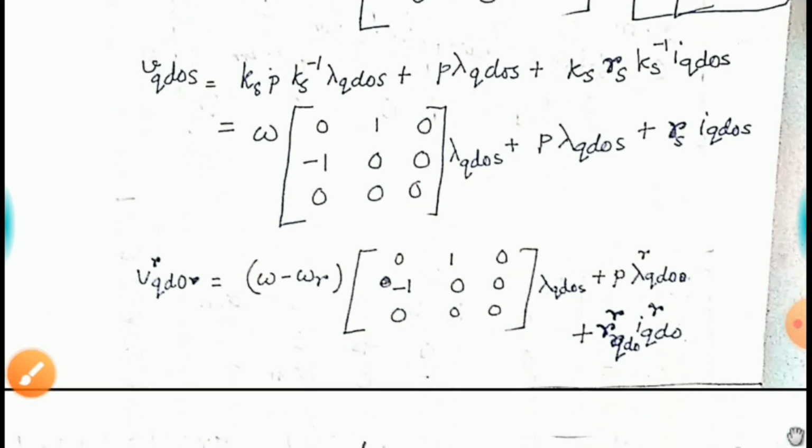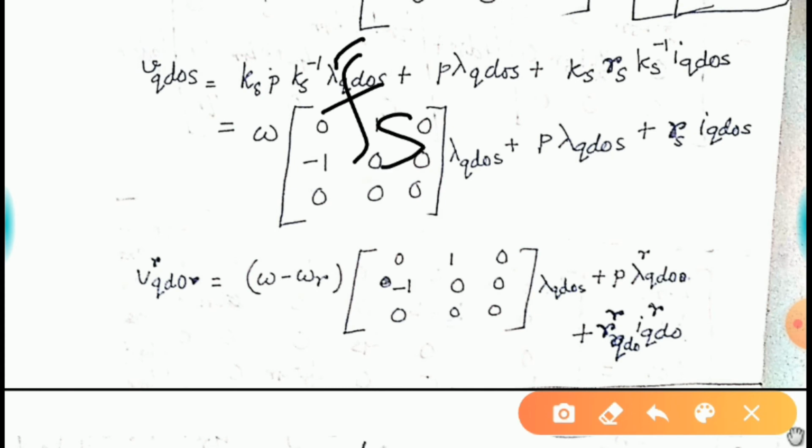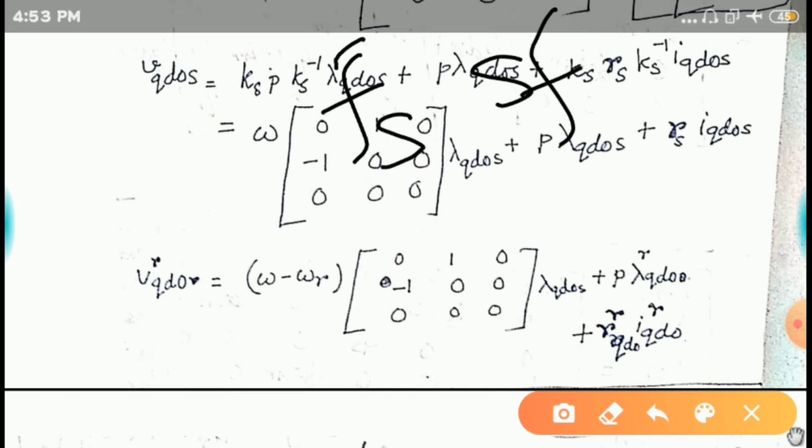But when we are dealing with the rotor quantity, the rotor is not standstill. Do remember that I used to remind you several times that this is the sole reason that allows us to draw phasors of two apparently different frequency signals on the same graph. The stator frequency is Fs, your rotor frequency is SFS.